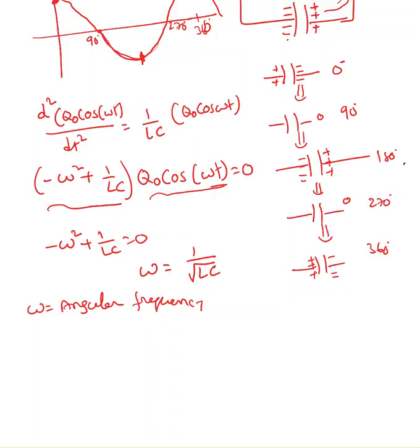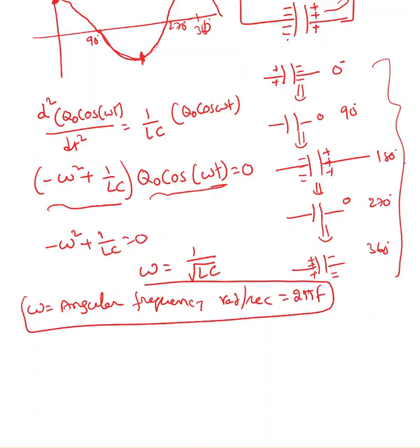This is nothing but how many times, and this is one cycle. So how many times it's going to rotate, or charge is transferred from capacitor to inductor, inductor to capacitor, in 1 second. That's what it's going to tell you. Angular frequency is in radians per second. So how many radians it is rotating in 1 second, which is nothing but 2 pi f. Omega equal to 2 pi f. You need to remember this all the time.